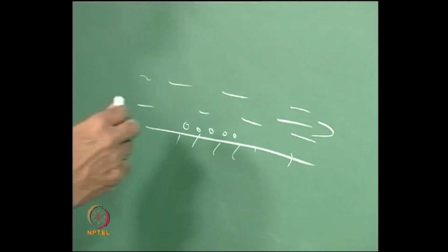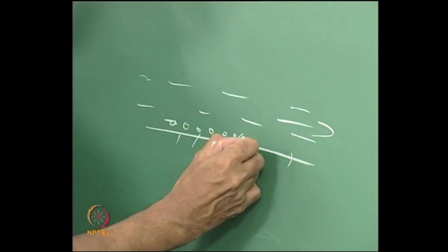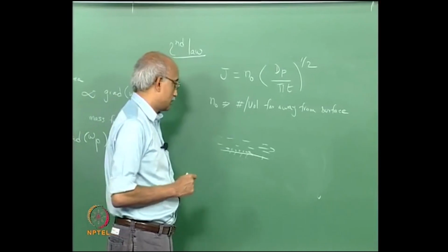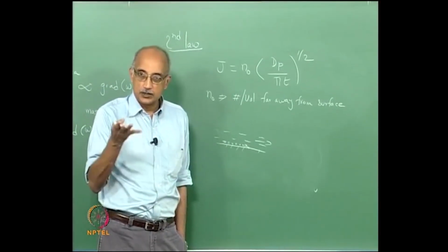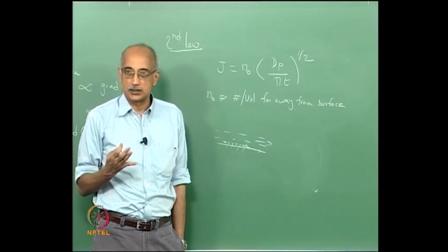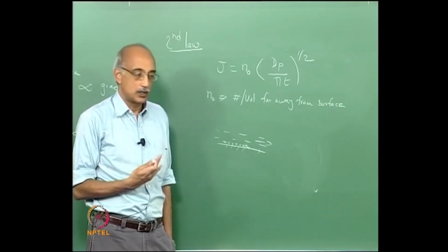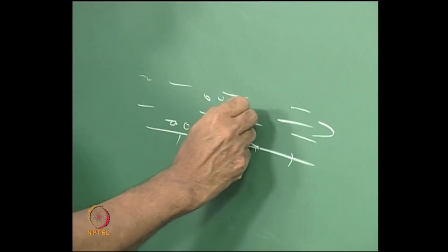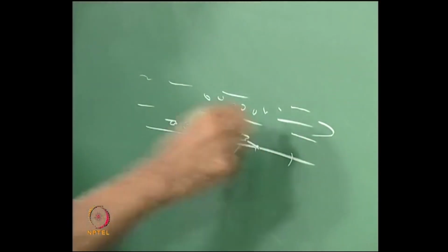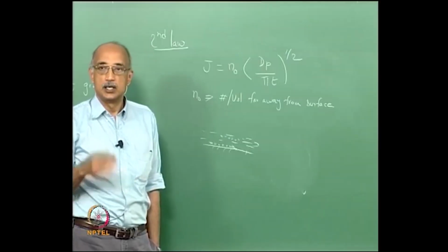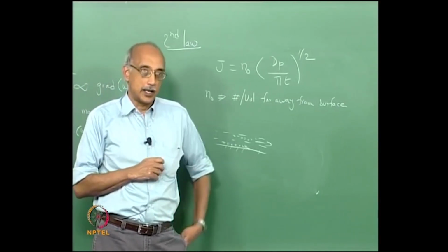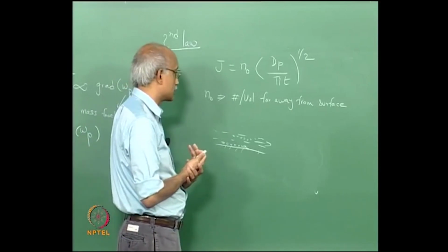And similarly, particles that are flowing adjacent to the surface have a tendency to touch the surface, develop an adhesive force, and thereby become attached to the surface. So what does that create? It creates a concentration gradient because you have a large number of particles in the mainstream, far away from the surface, but you have fewer particles in the gas phase or in the fluid phase adjacent to the surface, and that is what sets up your concentration gradient and initiates your diffusion process.